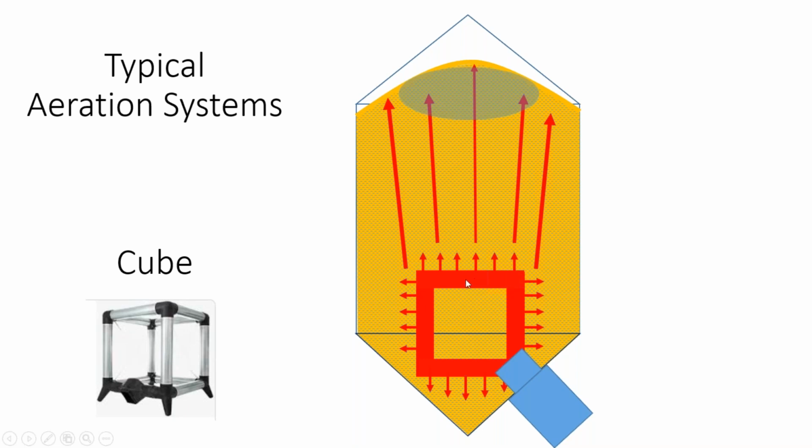So this should be a very efficient way to get air into the bin. I also like the fact that you are injecting a lot of air into the core, so that any of those fines that might be hindering your airflow are basically negated by having excessive air.